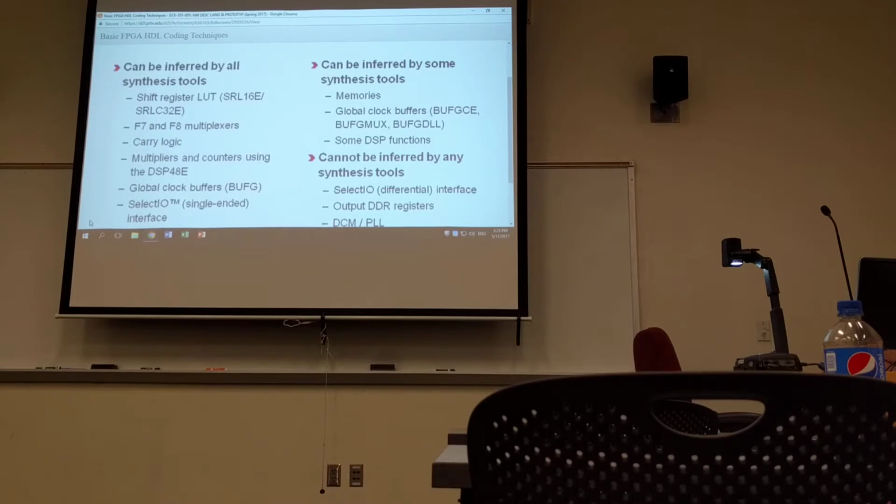You should also note that even if you were to build an appropriate shift register component, your synthesis tool may still require you to place an appropriate attribute in your HDL that will tell it to map to the SRL primitive. So one of the most helpful skills a designer can have is to have enough experience with their synthesis tool to know the appropriate attributes and its appropriate coding style limitations for that synthesis tool.